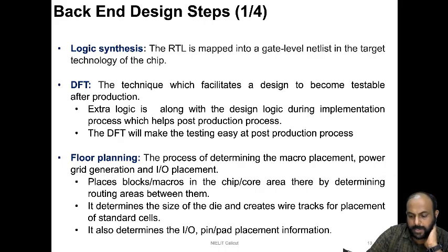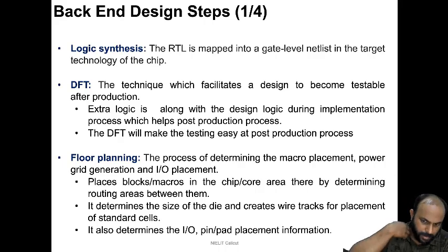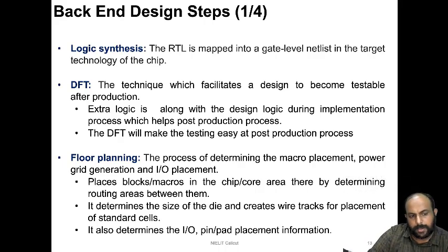It's just like we are building a house. We need to first decide where should be the bedroom, where should be the dining room, where should be the family living room, where should be the kitchen, and so on. Also we have to plan where the power should come in, where should be the exit and entry, and so on. So IO placement, power grid generation, macro placement, everything happens. It's not actual placement, it's about determining where it should be placed. So those steps happen in the floor planning stage.